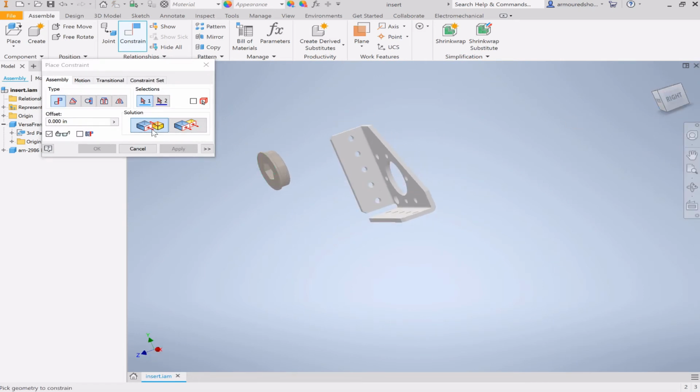The other use case that I like quite a bit is that you can use it to align two holes and make them concentric. Like that. Those holes are very different sizes, but now they are aligned with each other in a concentric fashion, which is great. You can also use this for mating VersaFrame. It's fewer constraints than trying to fully constrain it with mate and flush. It's your call. Sometimes tolerances don't quite line up and you have to do it the long way, because if CAD is 1/1000th of an inch off, it doesn't like it at all. So yeah, those are basically the use cases.